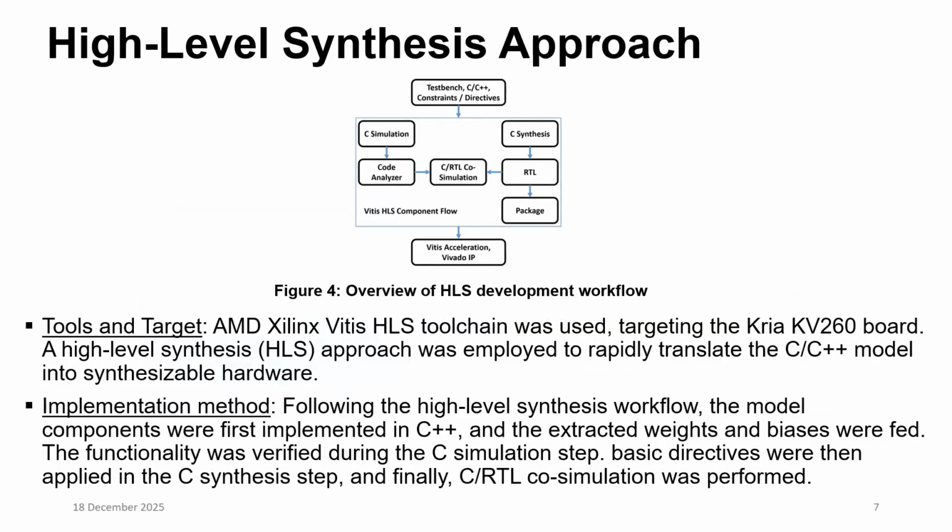The second step was to implement this model and deploy it on the FPGA. We have two options: go through RTL implementation, which could take some time due to the complexity of the transformer model, or take the high-level synthesis approach. With high-level synthesis, we implement our model using the C++ language.